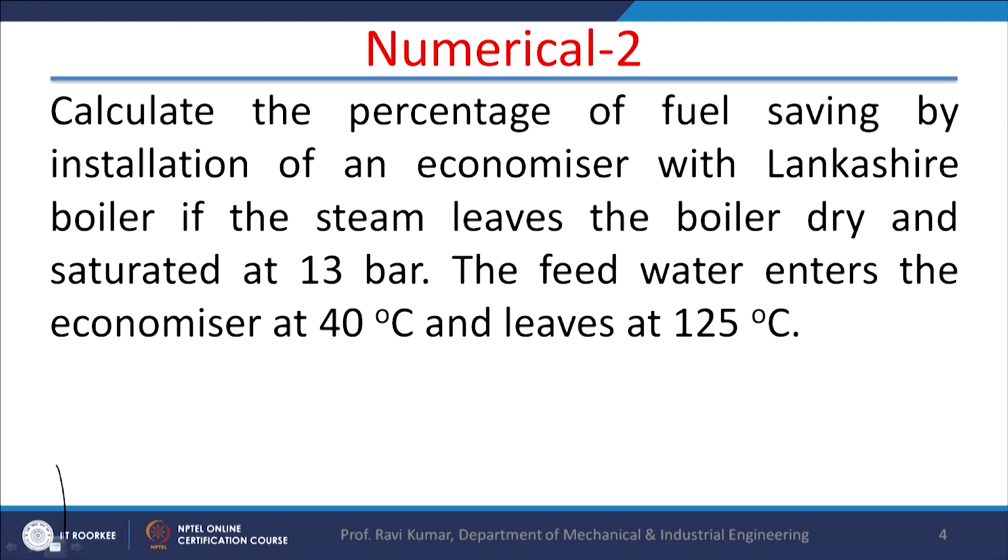Now, if you remember, the position of the economizer is that it comes into contact with the flue gases. When the flue gases are leaving the boiler, then the economizer is fixed. So, feed water which is going to the boiler is heated in the economizer. Feed water earlier was going in the boiler at 40 degrees centigrade, now it will be going at 125 degrees centigrade, and that is going to be the saving in energy in the boiler.